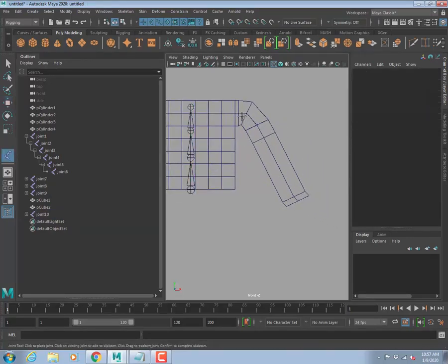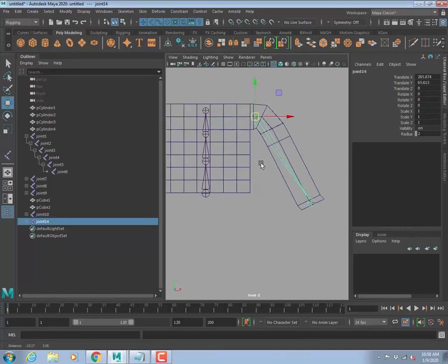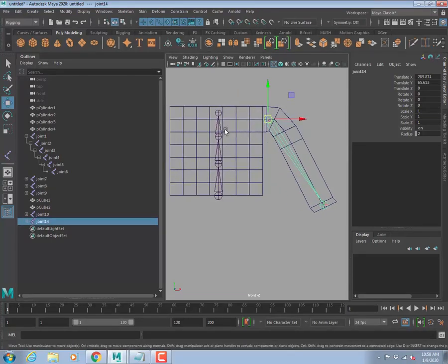Over here I need to draw another joint. Let's say press G. At the shoulder normally you have one, at the elbow you have one, and at the wrist you have one. Just imagine this is just one line. Then we will connect this to whatever joint we have on the body, at the backbone, let's say. So I Shift click this, and then I press P.